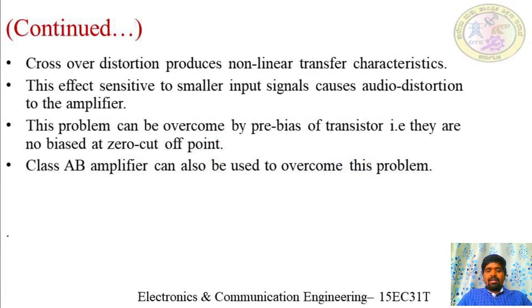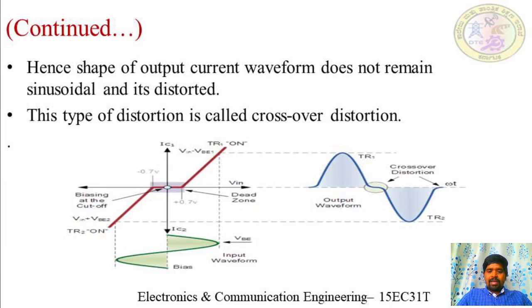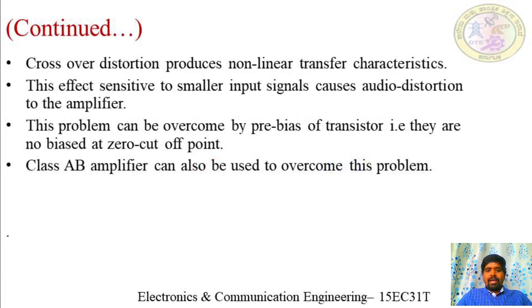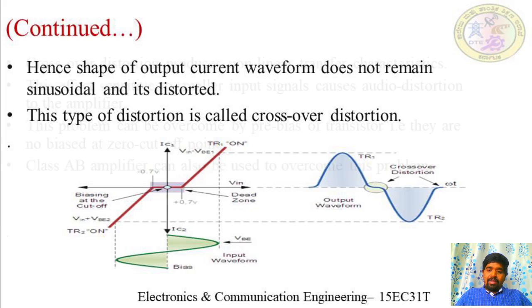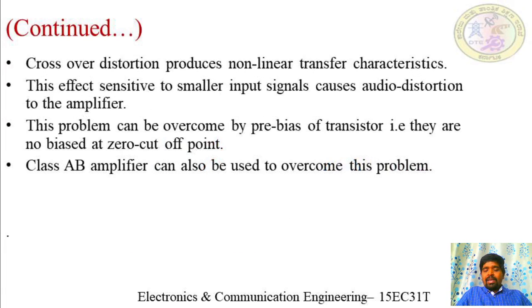And this is what I already mentioned. Crossover distortion produces non-linear transfer characteristics. Yes, here the transfer characteristic is not linear. And second, this effect is sensitive to smaller input. When the input signal is very high, this crossover distortion will not have any effect, whereas if the input signal is small, it will affect crossover distortion. That's why they are saying this is very important. This is sensitive to smaller input signal.